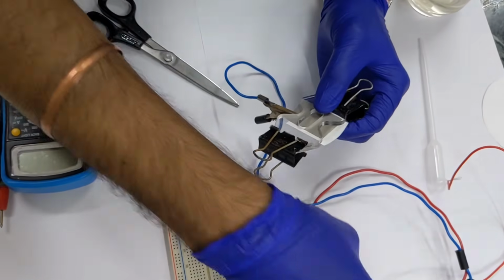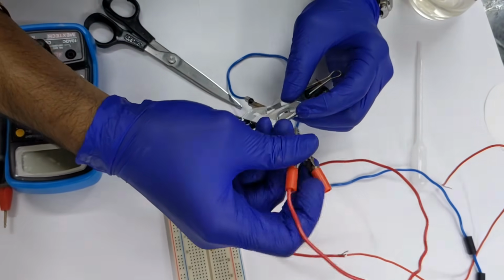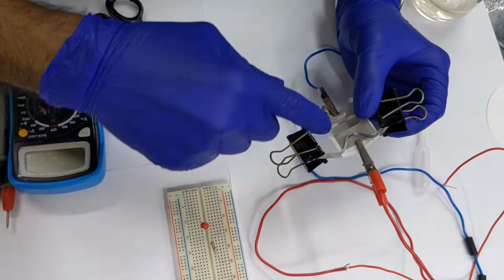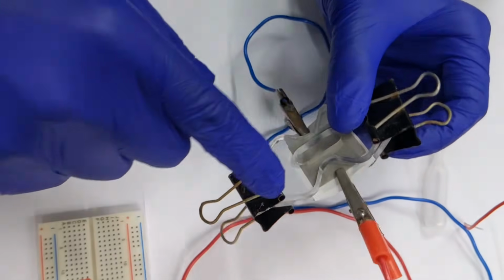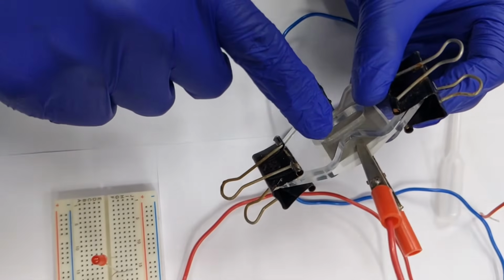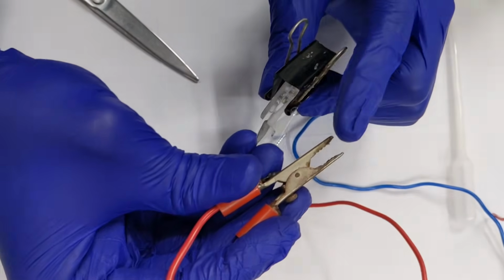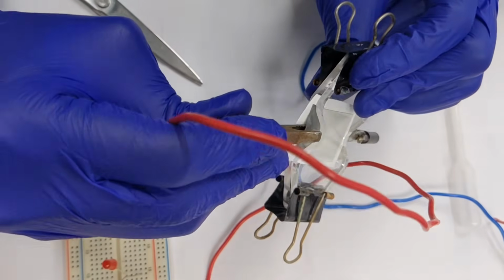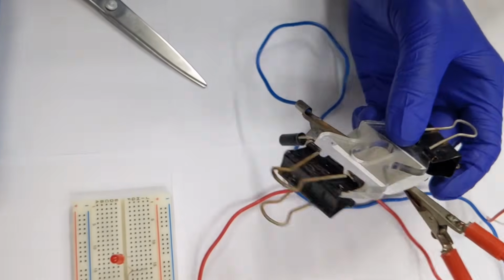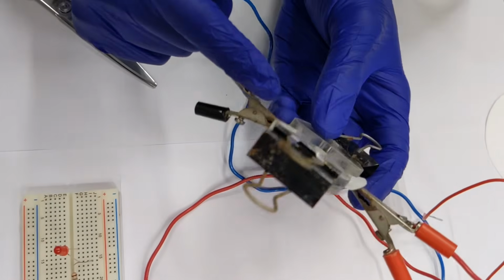When you connect the electrodes, make sure that you do not connect two electrodes at a time. For example, if you connect this way, it will short circuit, like the stainless steel and the zinc are in contact with the single electrode. It will create problems. Okay, make sure that one of the arms of this goes inside the separator and you clip the zinc in this way. Make sure no two electrodes are coming in contact with each other.